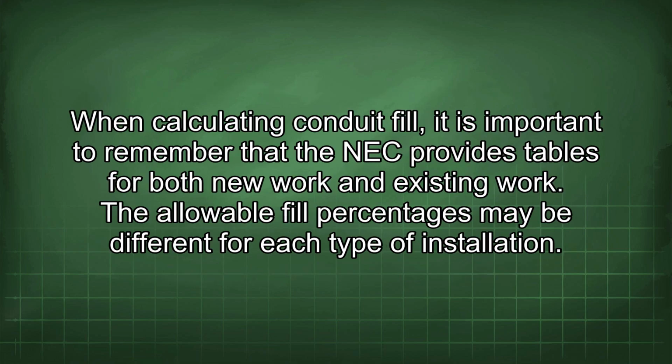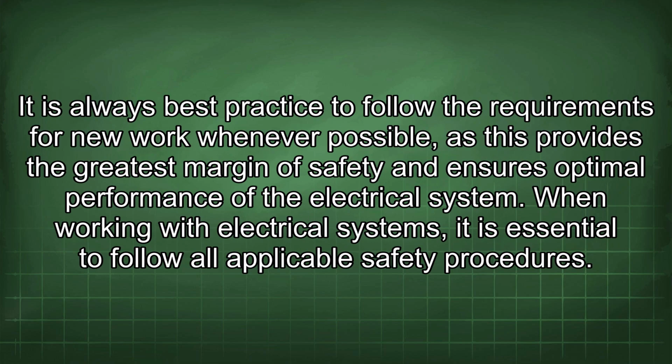When calculating conduit fill, it is important to remember that the NEC provides tables for both new work and existing work. The allowable fill percentages may be different for each type of installation. It is always best practice to follow the requirements for new work whenever possible, as this provides the greatest margin of safety and ensures optimal performance of the electrical system.